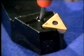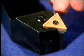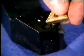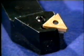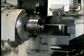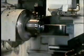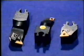Tungsten carbide inserts can be used for most machining jobs, and they're easily changed. They have several cutting edges. This triangular insert has 3 cutting edges on each side, a total of 6. Although inserts are easily changed, with the new CNC machines in use for high production batches, even these changeover times are considered slow. A new system is that of block tooling.